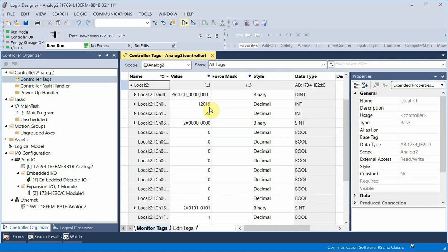It's off a little bit. It's off by about 20 there. If I go to 20 milliamps, it's off by about 78. So something's not linear. Okay, it's off by just a small amount. I suppose if I was overly concerned, I would try to write an equation that could flatten the curve and make it more linear.